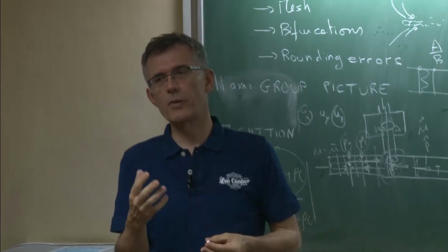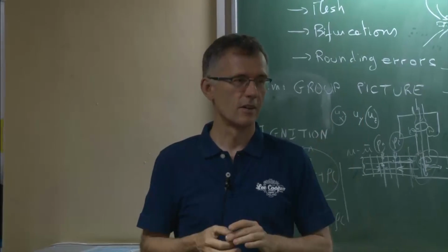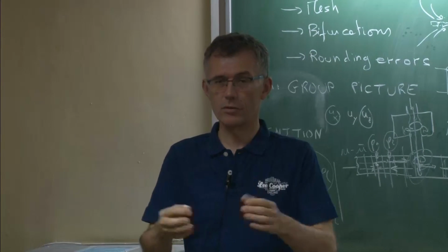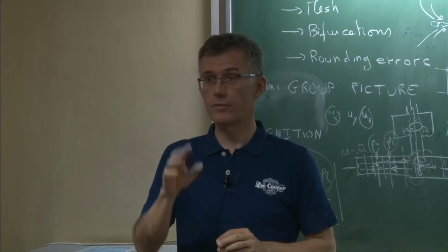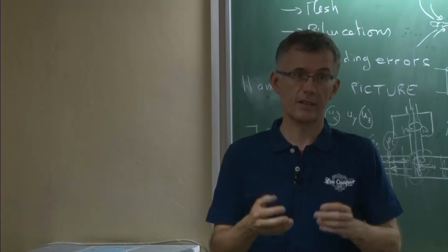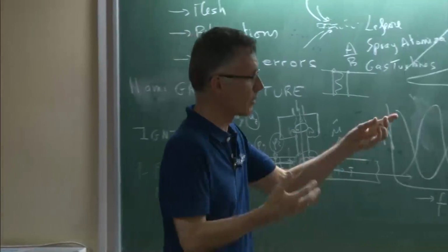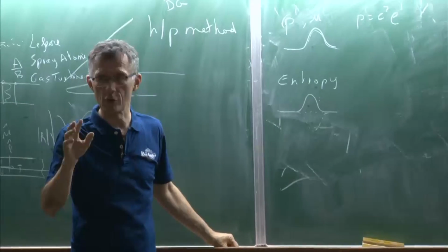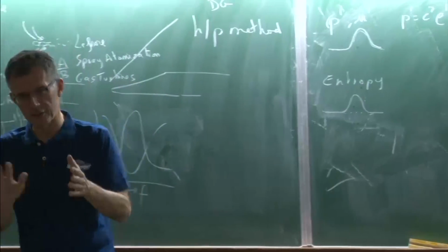The name entropy wave looks a little bit too complicated. We should call it a hot spot. It's a hot zone locally, and it doesn't make noise. There are no acoustic waves associated to entropy. That's exactly the way we do the demonstration. They are independent waves in the linear regime for constant velocity.